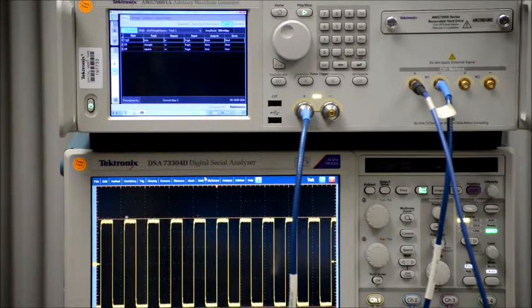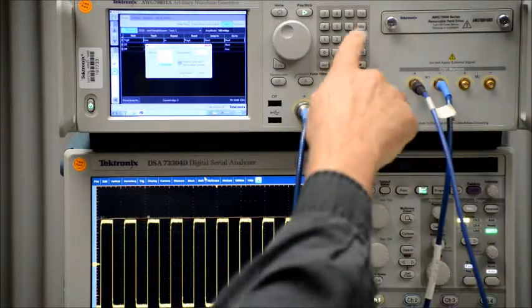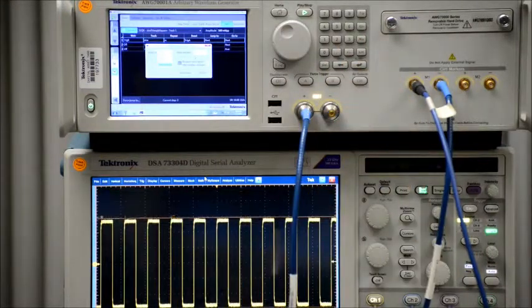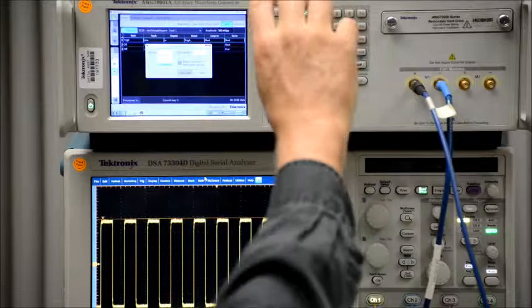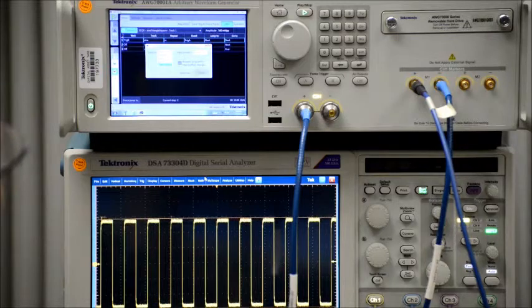It allows you to go through many waveforms, and what we can do also is, say you want to go to a particular waveform in the list of waveforms that you have here, rather than going through them sequentially. You can pick a waveform number and then go to that particular number. So if I put in 3 here, I can go ahead and select jump now, and it goes to the square wave, which is index 3. And you can also use a general purpose knob if you want to just scroll through these events or these indexes. So let me close this.